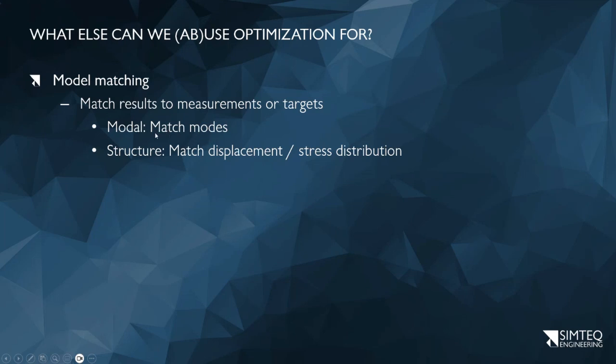Now the weight for that little equation comes in. What happens if I've got 10 modes that I need to match? Then I'll write 10 separate equations, mode 1 frequency minus the measured frequency squared, and do the same for every one, but I specify different weight factors for each of them. If all of them are equally important, I'll make the coefficients 1. If a couple of the modes are really critically important, I can just increase the weight a little bit to try and improve that matching.